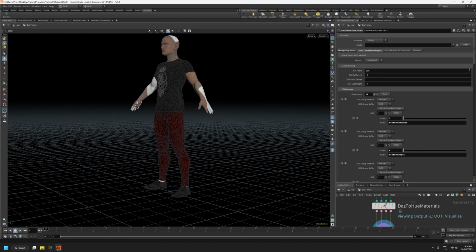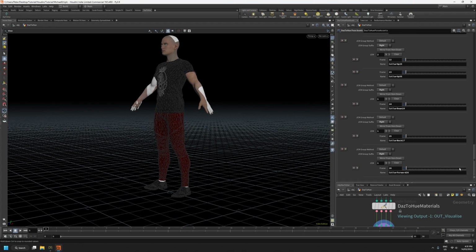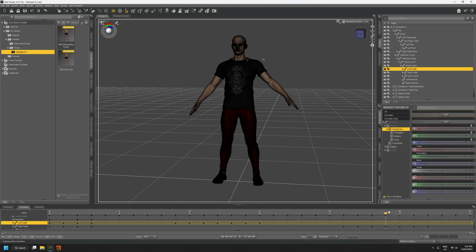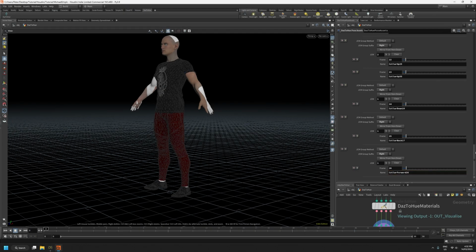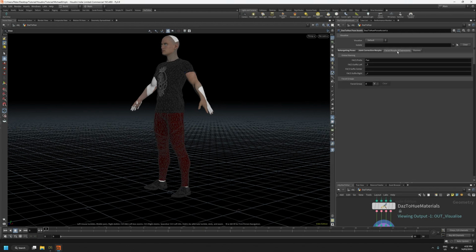We'll click the button. Now if we scroll down, you'll see now at frame 15, we are going through the same range of motion, but this time for the right-hand side. And so just to double check everything's worked properly, frame 26 should be our right collar, forward 26. So in Daz, if we just have a look at frame 26, you can see indeed our right collar is forward 26 degrees. So that's worked. So that's it for setting up this, albeit simple, range of motion. For the joint corrective morphs part anyway, we still have our facial expressions and speech shapes to work with.